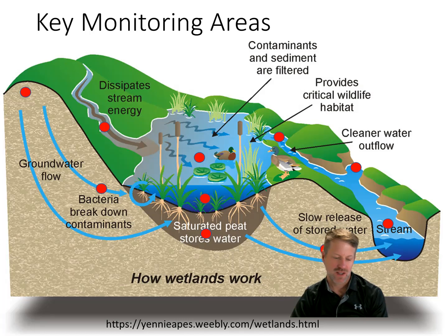So I also want to highlight the opportunity to cross-train biologists with how to maintain sensors as well. So that the most expensive part of environmental sensing and monitoring is actually the labor to go out and maintain that sensor. So if we're already sending biologists into the field to collect macroinvertebrate data, can they help keep the sensor clean? Can they just make sure that the measurement that it's taking is valid and give that eyes on the sensor?